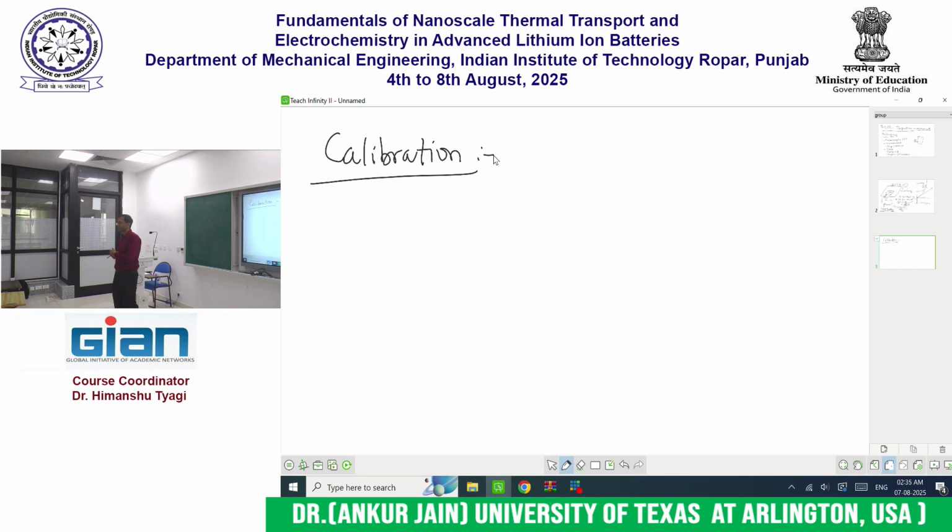So, for example, if I have a temperature measurement device and I want to use it to measure a temperature in the range of 20 degrees C to 50 degrees C, then even before I start taking my measurements, I need to expose it to known temperatures of 20 degrees C, 25 degrees C, 30 degrees C, 35 degrees C, and so on, and at each of those known temperatures, I want to measure the voltage that it is producing.